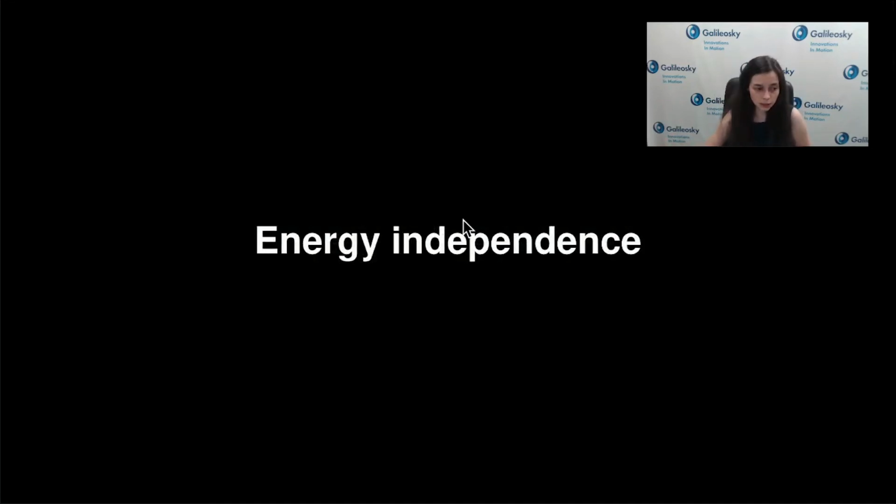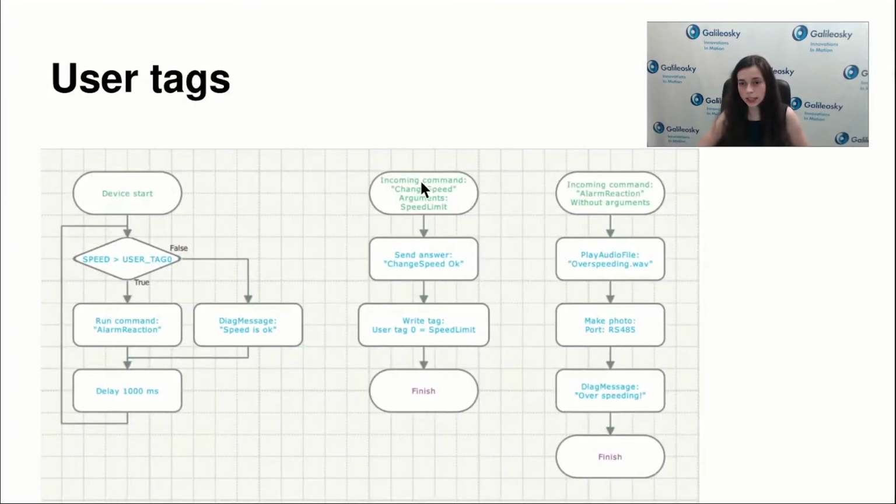In our previous example, we looked at sending some new information via SMS in order to change some things in settings. What is bad about it is that after a device reset, you will lose this information that was sent via SMS. So you changed the speed limit to 60, the device was rebooted for some reason, just the vehicle was turned off and on, and the device restarted. In this situation the device will have the 100 that was previously written in the Easy Logic algorithm global variables.